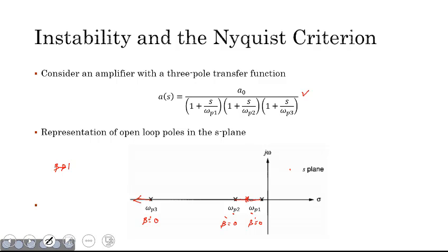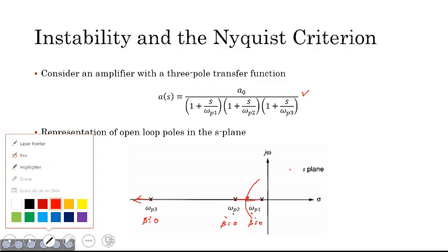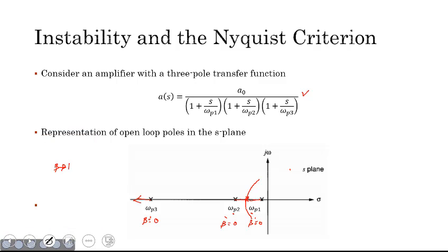And what happens after, as we increase the value of beta factor here? It's obvious that these poles will make a route which is something like a circle or a semicircle, right? They generally break away at this particular frequency at an angle which is basically 180 degree divided by the number of poles in the system, which is basically 60 degree.